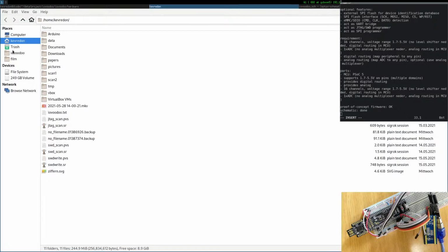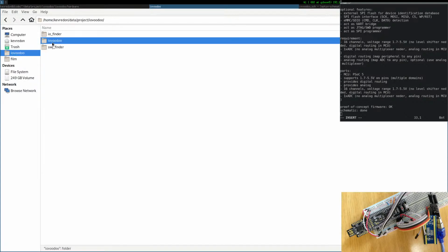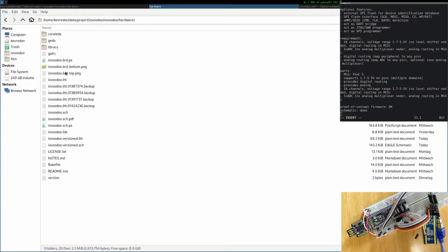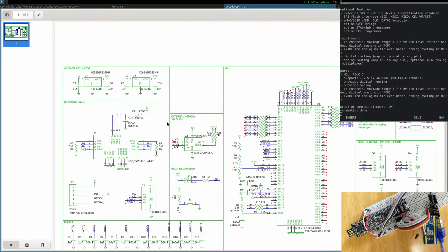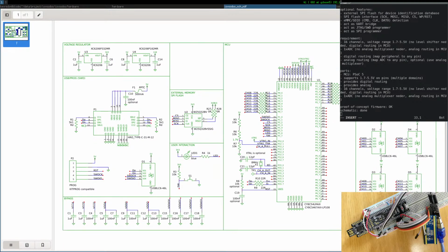And by print to hardware, we can see the output schematic generated automatically. This is not needed anymore. And the output schematic is generated. You see that the script puts in the version, which is done by hand, and then the revision, which is the number of git changes there were on this file, and this is the git hash, and this way I know exactly which this corresponds to.